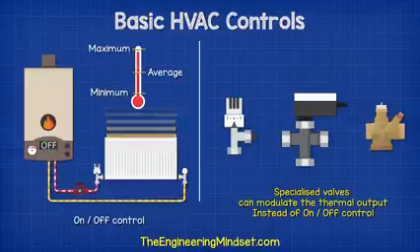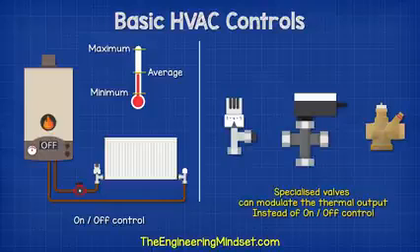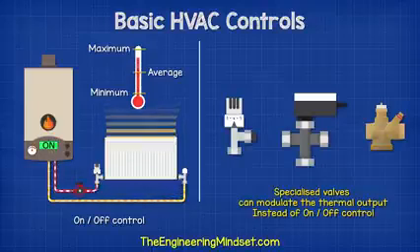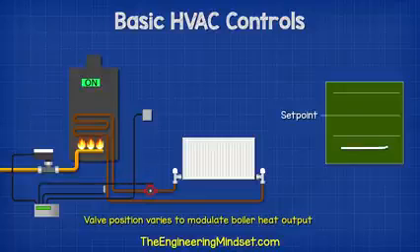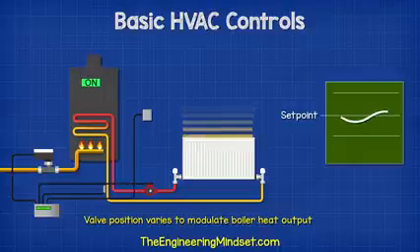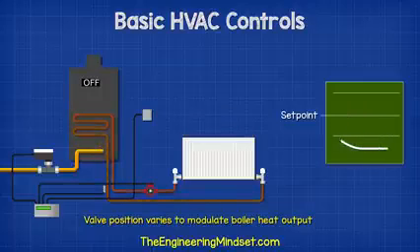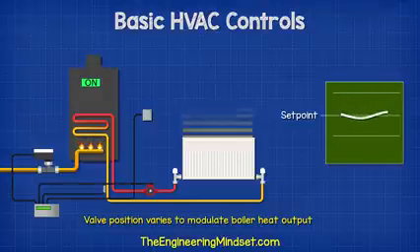On and off control makes it difficult to maintain a desired temperature. Instead, we can use special valves to modulate the thermal output, keeping the temperature within a certain deadband. In a simple heating system, when the gas boiler turns on, it will run at full power to heat the water, but then it reduces the gas supply by using a motorized valve. This reduces the heat output of the boiler. It does this instead of turning it off. The water temperature set point is kept in the dead band, so the heat output is equal to the heat leaking out of the room.